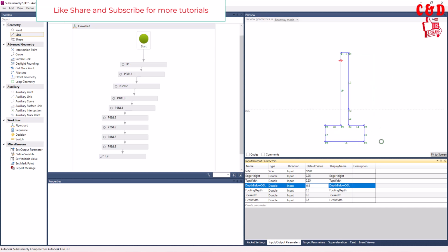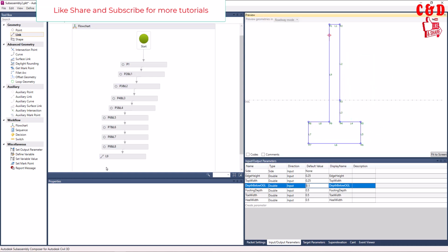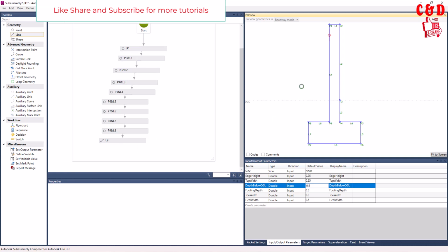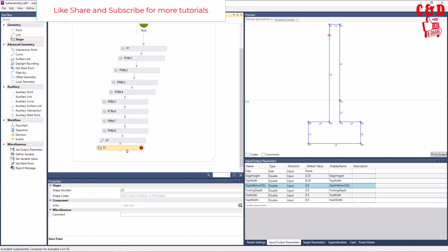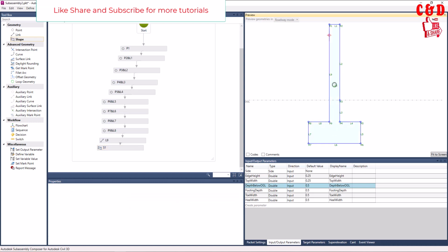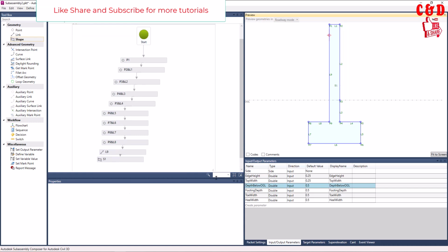So now the last thing we have before importing this and testing it with our Civil 3D, we have to define a state. So we drag it again and we define the state. For that you have to add each link. You click like this here, or you just select it. There is a button, you select and then move inside, and see it's highlighted. That means it's closed. So just click on it and you see S1, you say the same and no error, that means it's accepted.